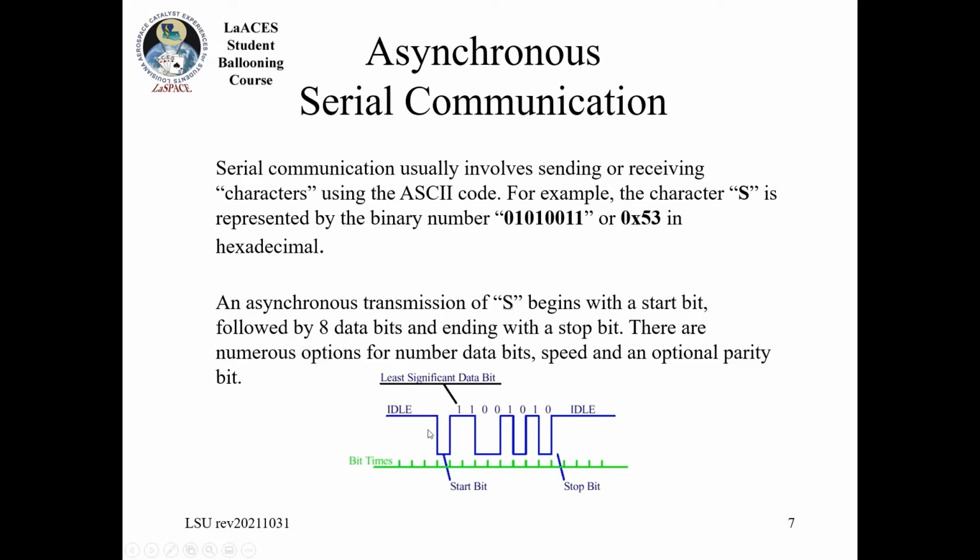So you'll have what's called a starting signal, or a start bit, so that whichever device is starting the transmission does that, and that signals to the other device that it needs to start counting based on its clock rate. And then after that, you'll start sending the bits. In this particular case, it's sent from the least significant bit to the most significant bit.